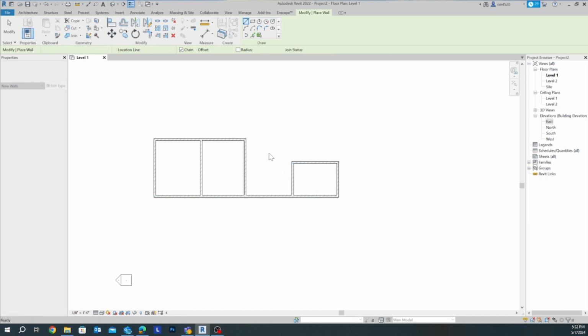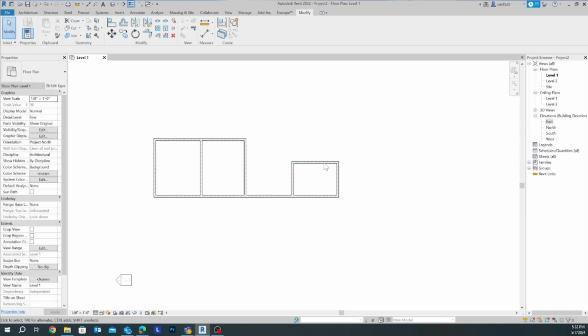And now I want this to be connected with this. How am I going to do that? So I'm going to click over this trim tool, click over here, and click over here. See, the dotted line that is created would just connect them all together. So that is how you can use this particular trim tool. All right, so that was pretty easy.